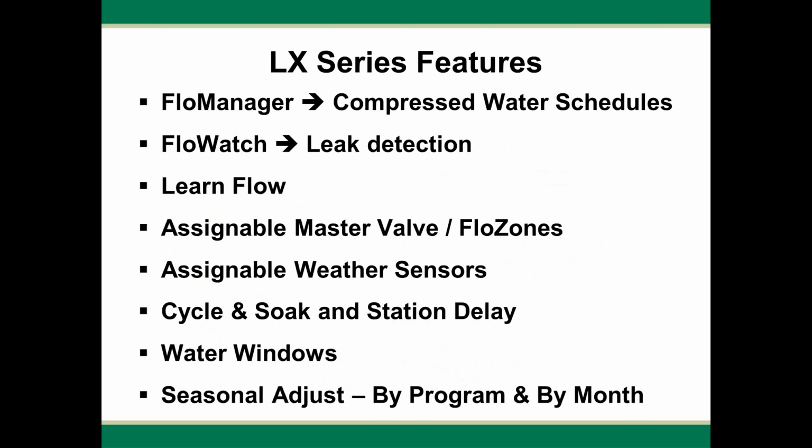We can implement cycle and soak and have station delays per station. We can create water windows to help us better manage when we want irrigation to happen on our site and make sure that no irrigation happens when we don't want it to. We can do seasonal adjust, not only by program, but we can also do seasonal adjust by months, and we can do both of them at the same time.